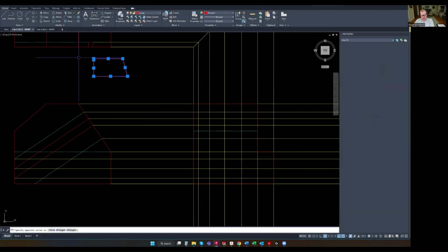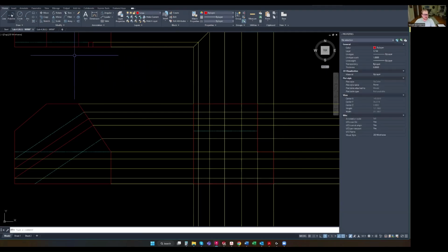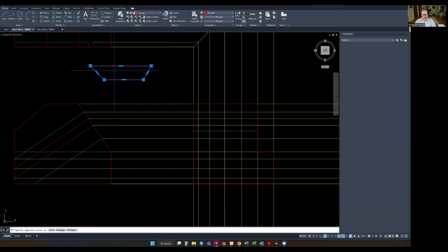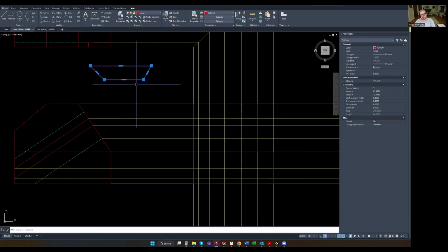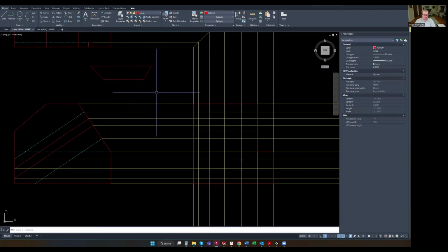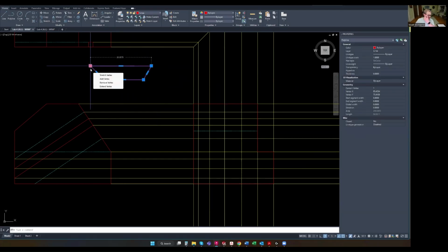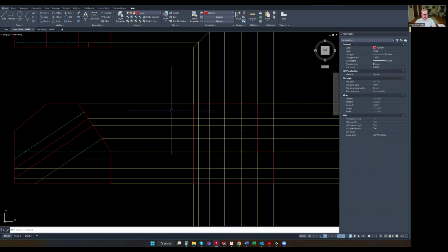When we use the polyline tool, which you can just click here, or you can type PLINE, anytime we create all those lines like that, it's going to pre-join them. So that's one benefit to using the polyline tool instead of the line tool. And I think this is the first time we've actually used that instead of creating polylines by joining line segments.